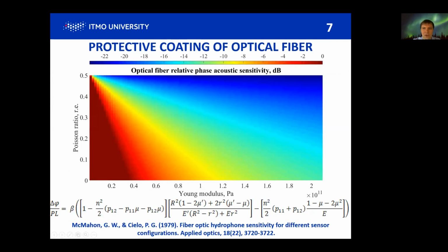the referenced articles. The next part of this research is the study of the possibility of reducing the acoustic sensitivity of fiber optic components by the implementation of protective coatings. In the literature, this method was also mentioned. However, for its successful application, it requires an accuracy of applying galvanic and polymer coatings at the level of micrometer units, which is a relatively challenging technological task. Failure to do this will significantly increase the level of acoustic sensitivity.